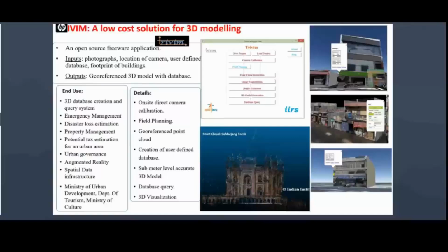The time of flight between the sending and receiving of this energy is noted down, and based on certain other parameters, the precise information about the target or terrain can be generated. The advantage of active remote sensing is that it can be done during day or night. It can compare the energy sent and energy received, so we can also know how much energy has been reflected and how much is absorbed, so we can know the type of target. And it makes mapping possible through the vegetation, in low contrast situations or shadow areas.